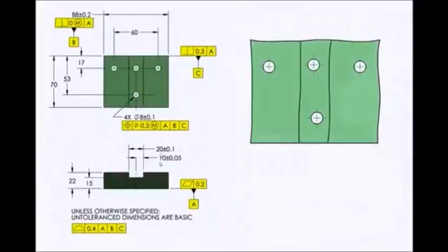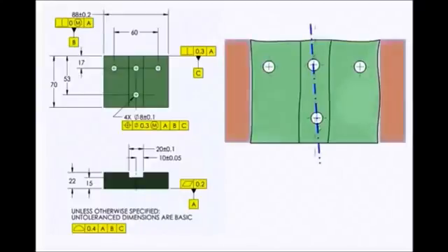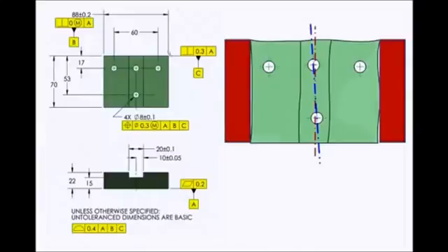If you did go with this 10 plus or minus 0.05, another question I would ask is, what am I measuring from? Is there some plane between these two holes that they want me to measure from? Or is it the center plane established by this width, datum feature B? And some people say, well, that's the datum feature. Yeah, but this doesn't reference the datum feature.